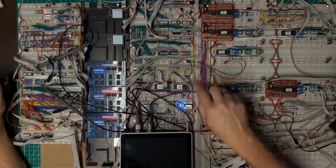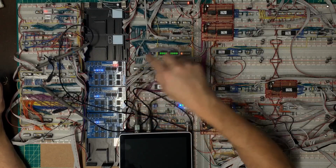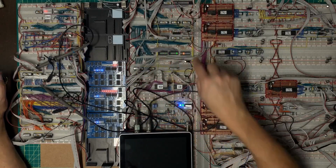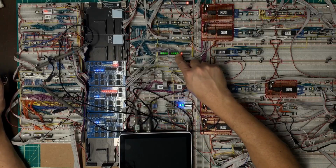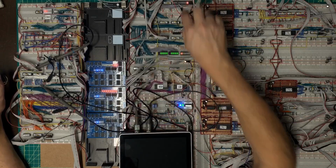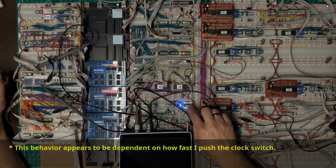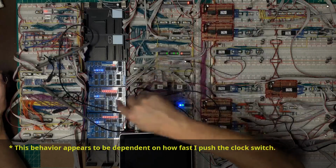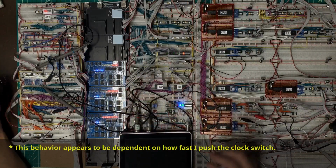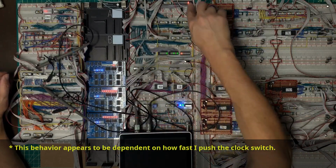Here's the next problem. This instruction is to load this value into R1 and then pass on a no-op, which it does successfully. This instruction is supposed to load this value into R2 and pass on a no-op up here, which it does successfully, sometimes. That same instruction passed on a load operation, which is to load this value into R1, which it did successfully. But it incorrectly passed on a 1 up here.